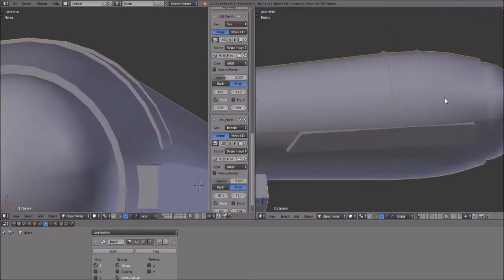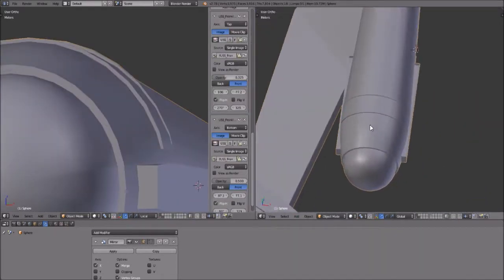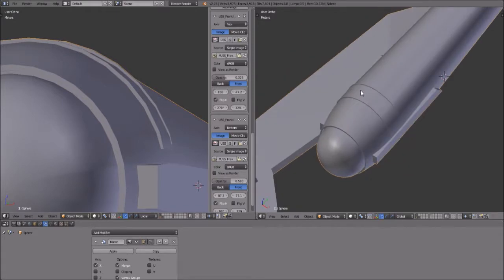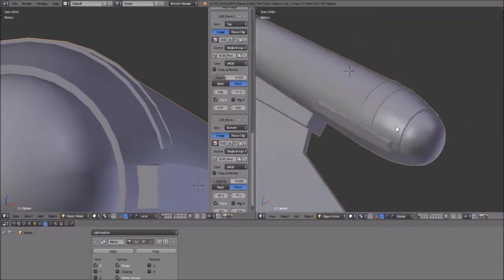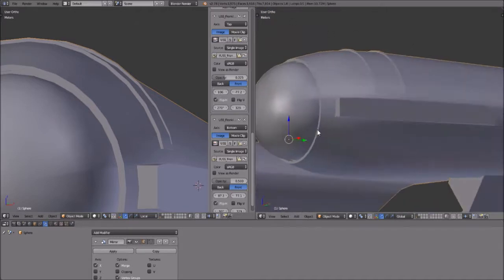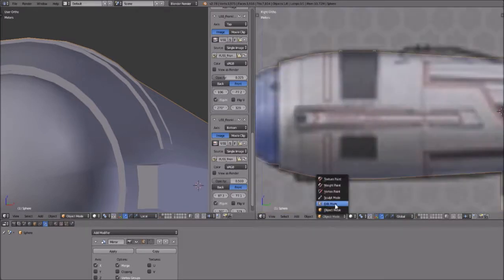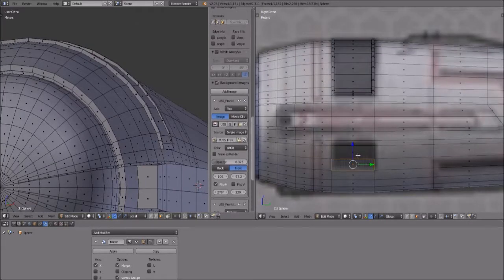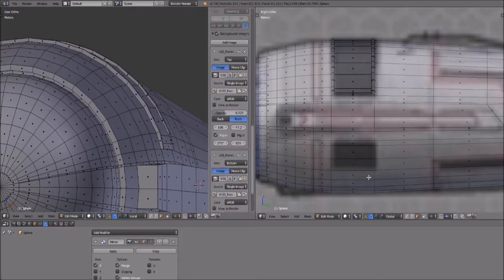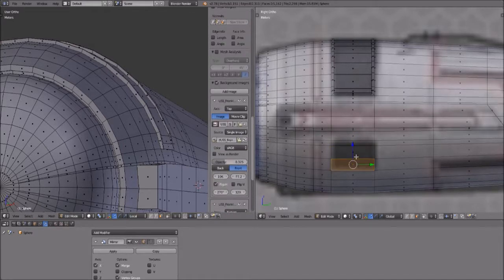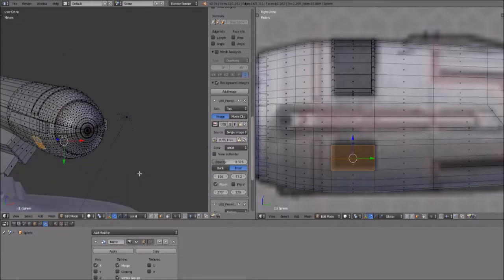Then from there, let's extrude all of those inset just a little bit right there. That should give me a little bit of a look for me to go in and put in the grill details. And we could do the same thing with everything on the side. Let's go ahead with these on the side, and it looks like I could pretty much do the same thing. Let's work on both sides at the same time by making sure that visible is unselected. So we should be selecting both sides.